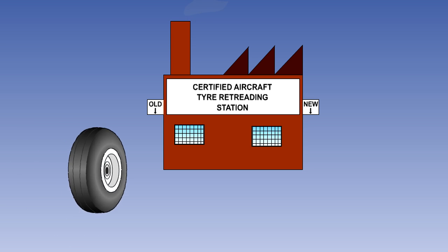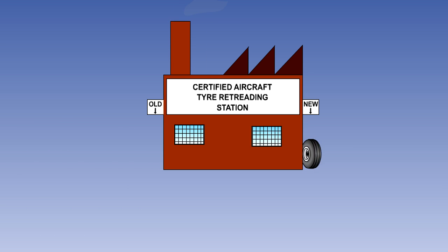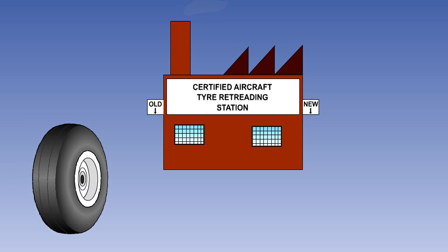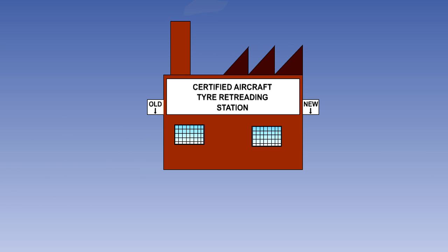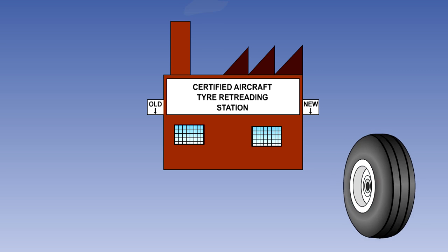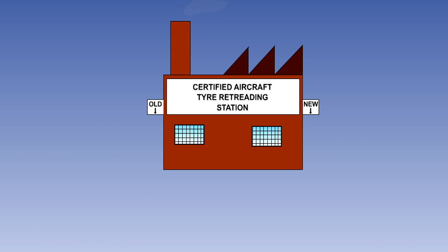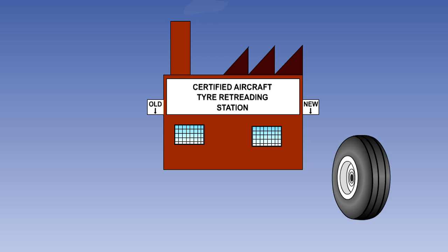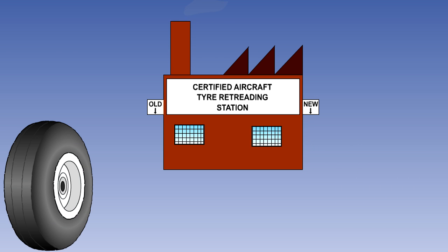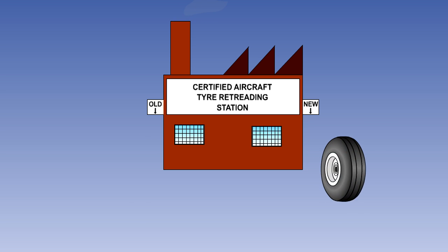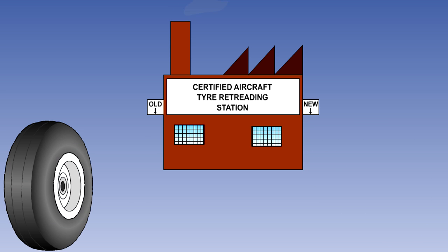Many aircraft tyres that become damaged in service can be successfully repaired. Tyres of which the treads are worn out, flat-spotted or otherwise damaged, but of which the core body or carcass is intact, can be retreaded. Retreading and repairing aircraft tyres has been a common practice for many years, and can save aircraft operators considerable sums of money.